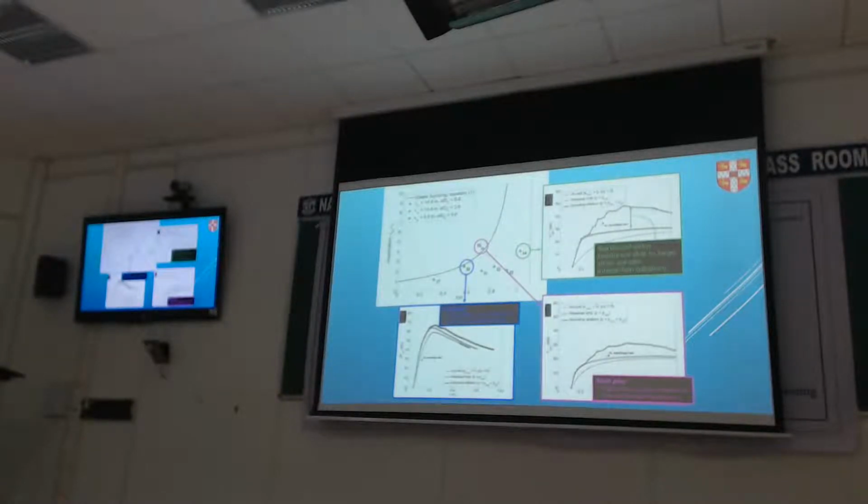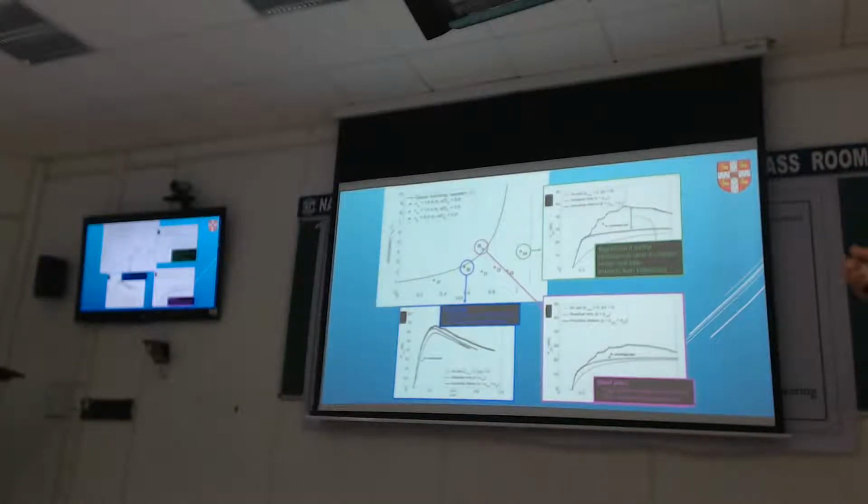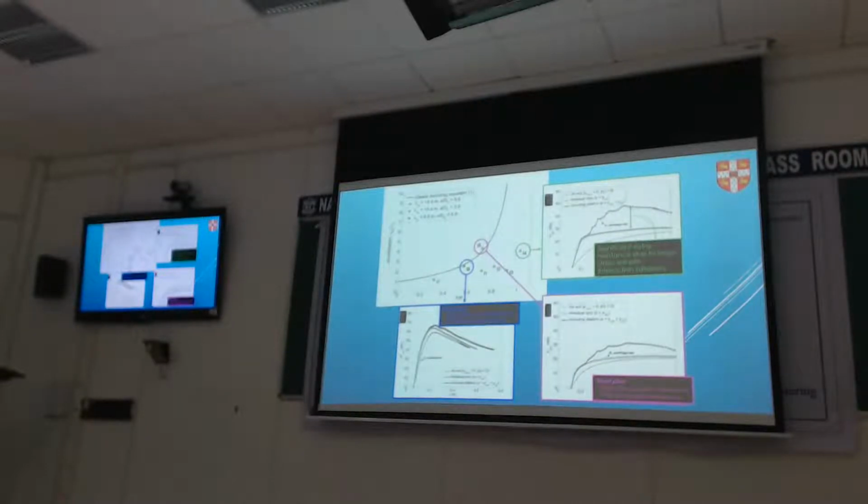So it is possible to use the PY springs in a modified fashion using this type of double curves and add the components you want to make up the solution which fits the experimental results. And then you can look at different load conditions and pile configurations. Happy?